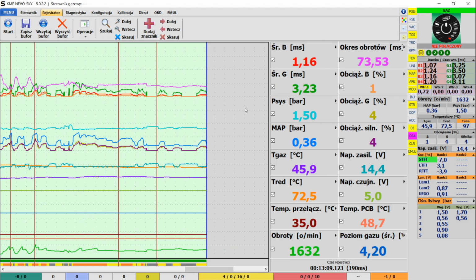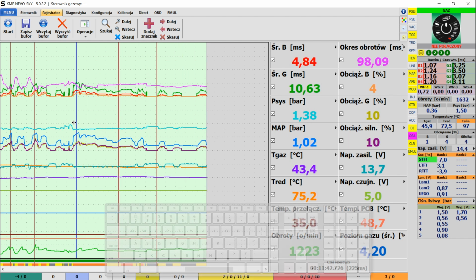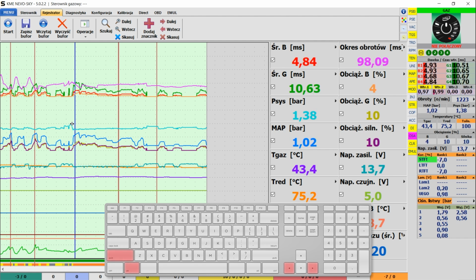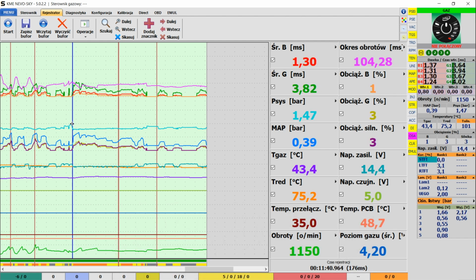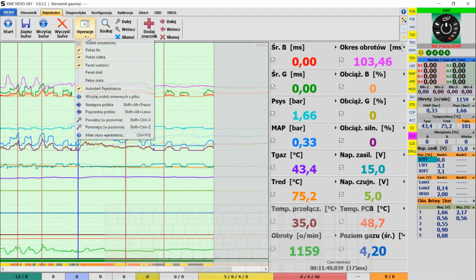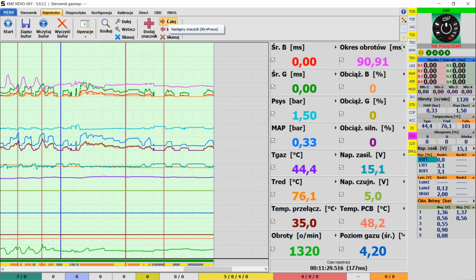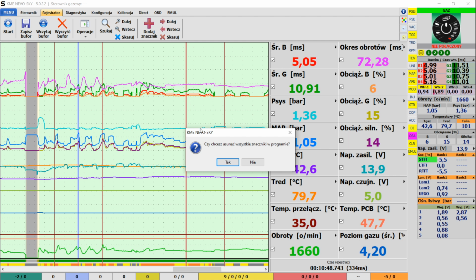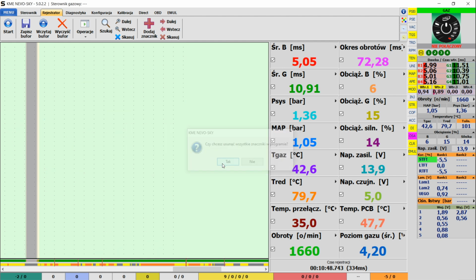To move the cursor of the recorder, represented by a vertical blue line, you can press and drag it, or utilize the shortcut with Alt, Shift, and the left or right arrow key. To navigate one sample at a time, you can adjust the zoom level of the recorder's view with the Ctrl-Shift-X or Ctrl-Shift-Z key combinations. You can find these and other options in the Recorder Options menu. Pressing the next or back button allows you to move through the markers. Pressing the delete button will erase all markers.